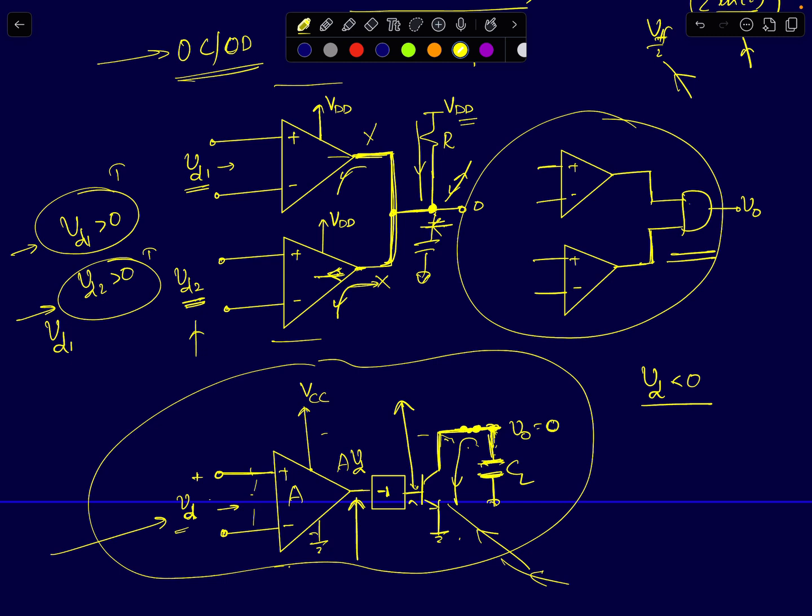If you recall, we were using logical AND gates in window comparators, and you will normally see, if I'm building window comparators using open collector or open drain output based comparators, you won't have to use an external AND gate. You can simply short circuit the two outputs and you naturally get this AND gate for free. That's another advantage of open collector and open drain output based comparators.